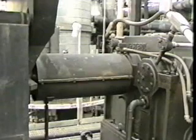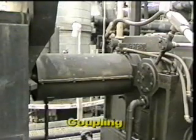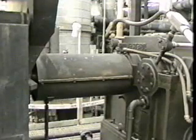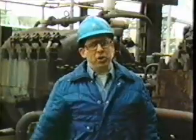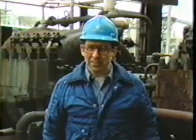The driver is connected to the compressor, or gearbox, through either a flexible diaphragm coupling or a gear coupling. The coupling allows for small misalignments between the two rotating shafts. And that's a typical centrifugal compressor. Now let's take a closer look at compressor operation.